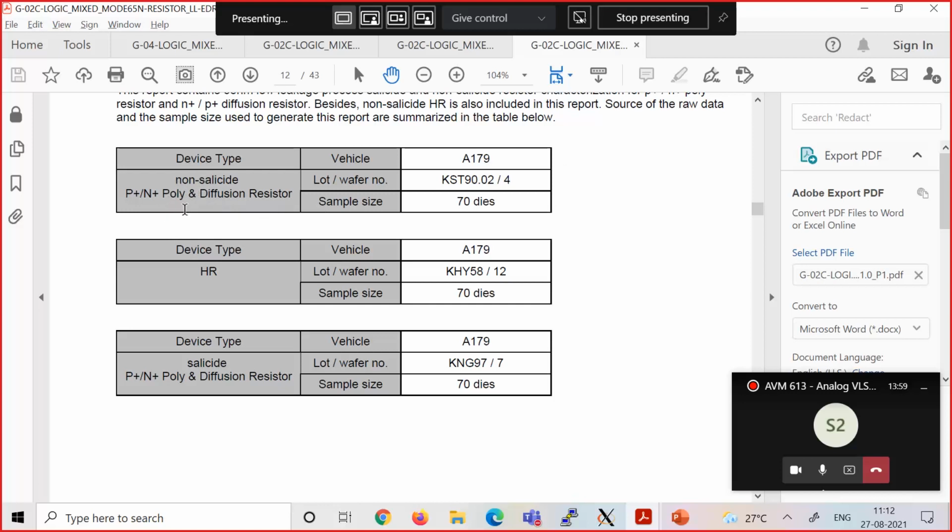If you remember, polycrystalline silicon is the material used for the gate. So you have the oxide layer, which is an insulator, and on top of that, some of the more modern processes use metal gate, but in this 65 nanometer process, they use polycrystalline silicon as a gate. That material can be used because it has a certain resistivity. You can use it as a resistor.